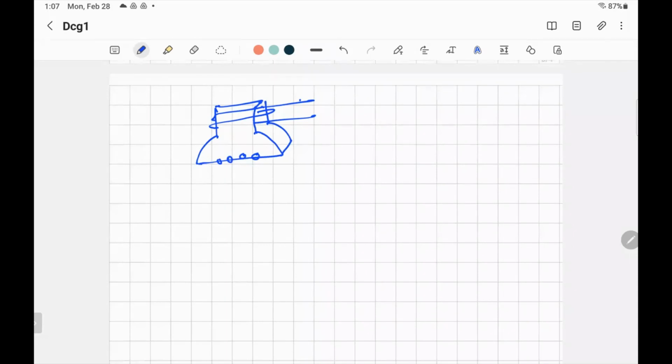And for a big DC machine, you have, for example, here one pole, and you have maybe another one. You have a 4-pole machine. So what do they do? They put small poles between them. They call them interpoles. So it's either you add this winding with the poles, or you have interpoles between them. But it's kind of expensive. They don't do it with the small machine, but they make it with the big machine only.